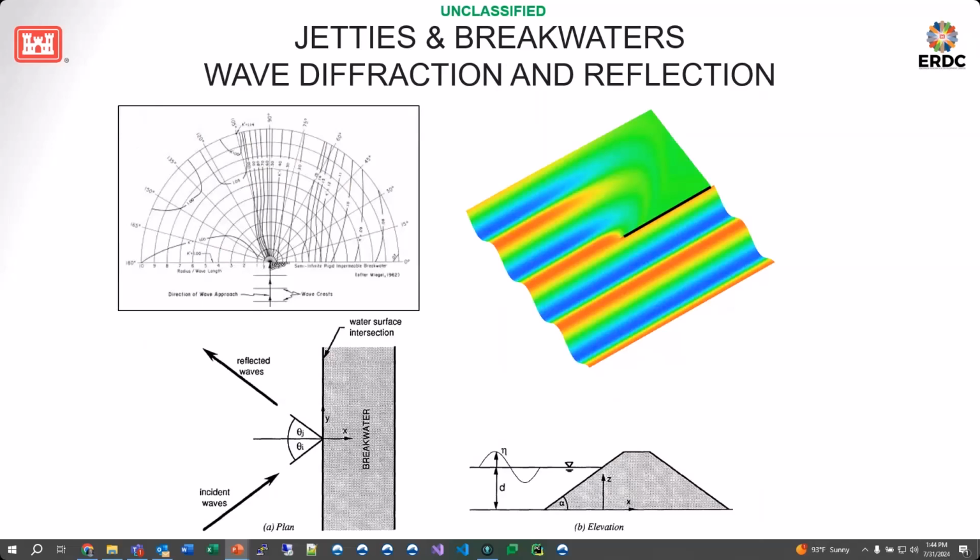So there's jetties and diffraction that we have capabilities for. So we have a jetty here, and then as the waves are coming in, there's less energy behind it because it can't make it over the jetty, but you do see some reflection and diffraction as it gets around the jetty and starts backing in this way. We have run a lot of different validation tests in testing this, and are pretty happy with the results there.